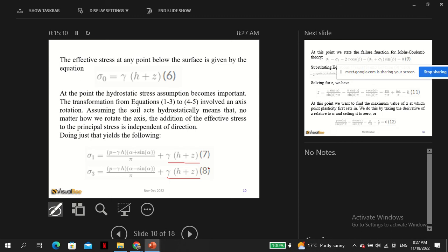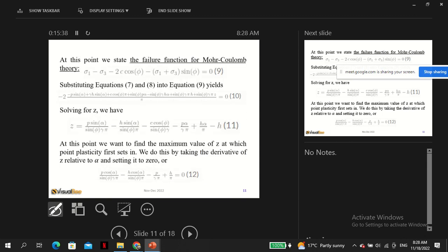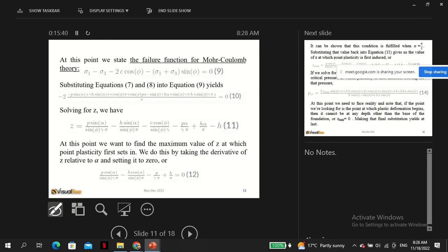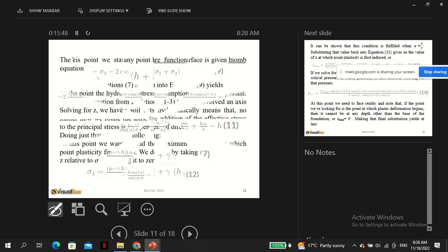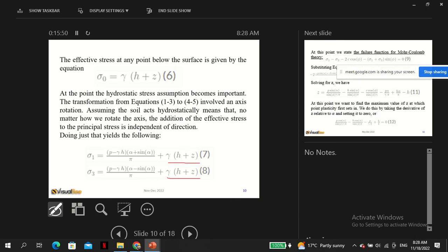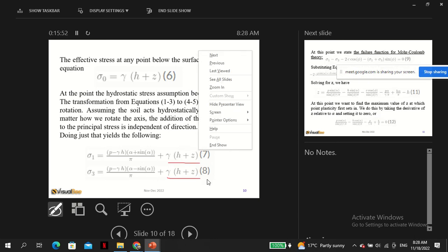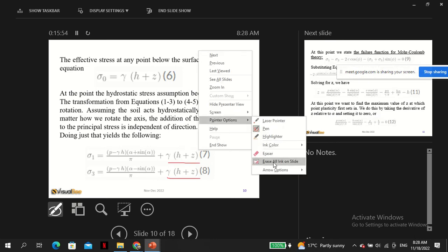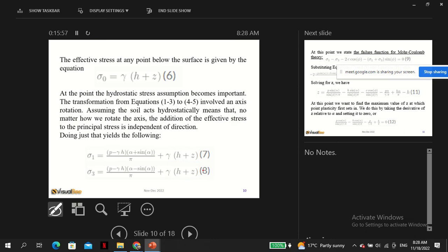If pressure is increased in every direction, then it means in every direction they are increased uniformly. So sigma 1 and sigma 3 become those values. And also remember that with these values the shear stresses disappear to 0.